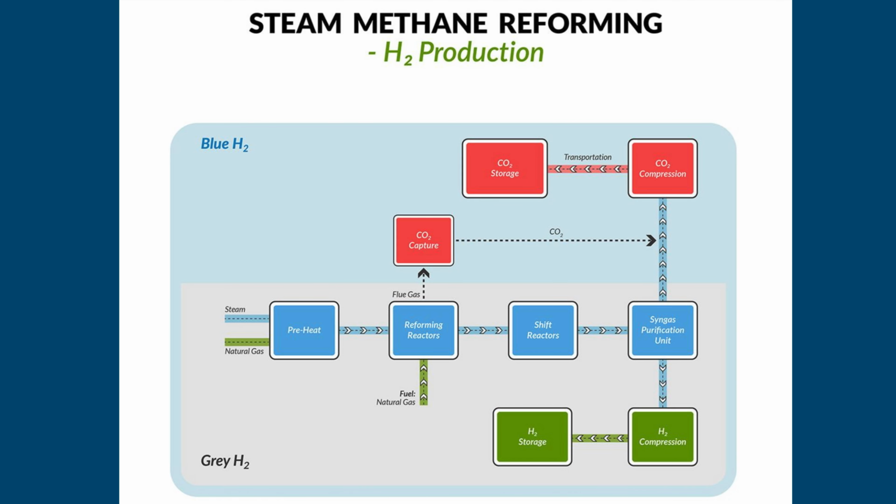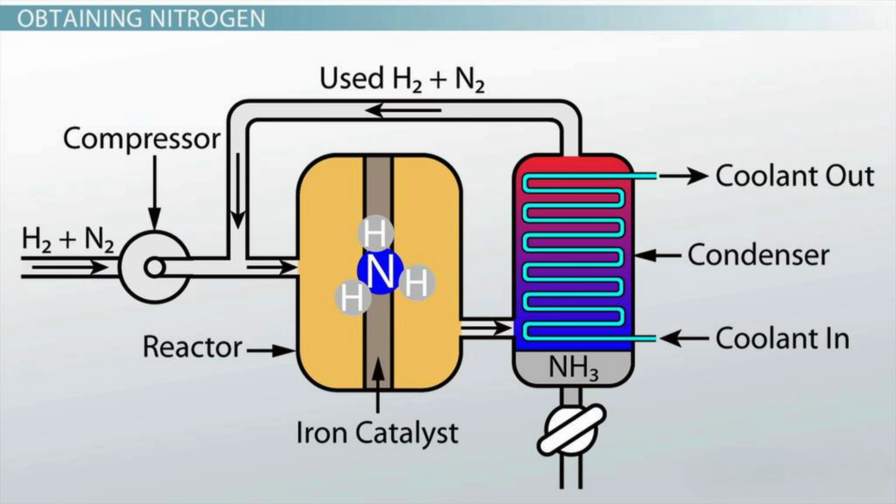upstream processes. While the chemistry of ammonia synthesis is well established, its industrial implementation is highly energy-intensive and deeply intertwined with fossil fuel infrastructure. Hydrogen is conventionally produced via steam methane reforming, making ammonia production a significant contributor to global carbon dioxide emissions. Modern ammonia plants are optimized for large-scale, continuous operation, relying on centralized production and global distribution networks.